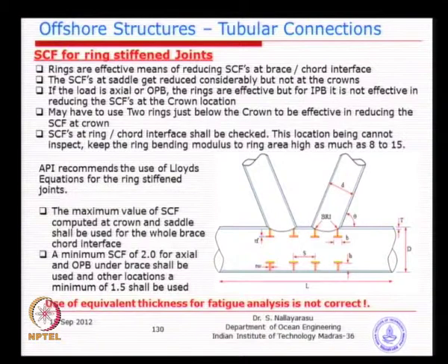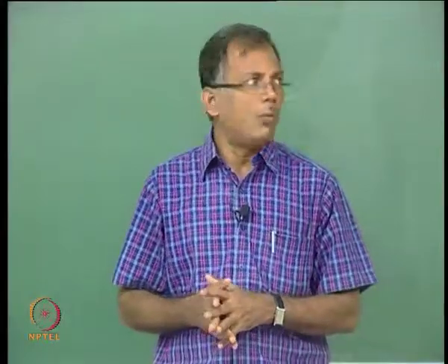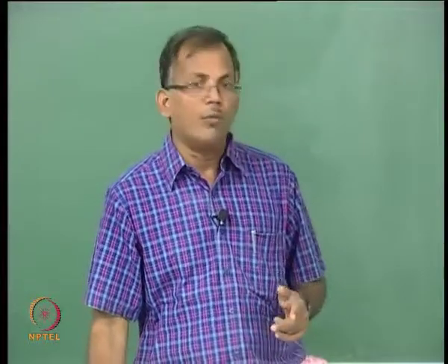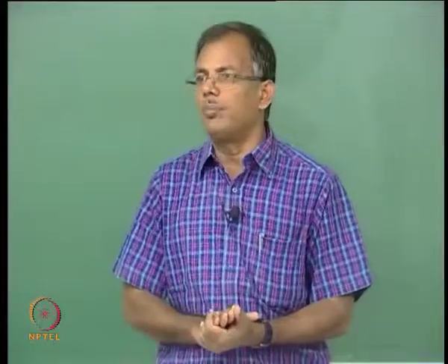But when you designed for static load, we never bothered about the stress concentration factor. What we were always looking at is the stiffening to avoid local failure of the chord from ovalization or local punching.